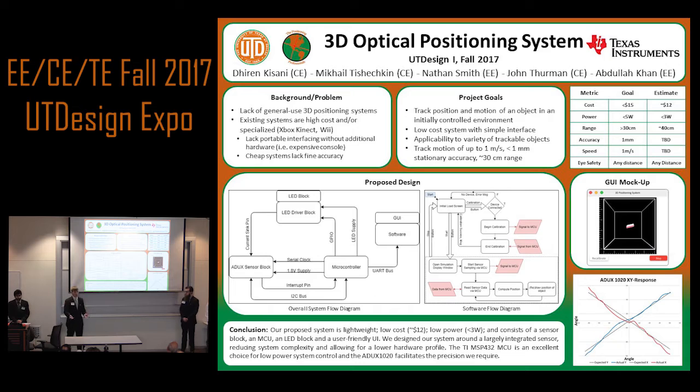It has the photo integrator, an integrated analog to digital converter, and an integrated LED driver. This significantly brought down the overall complexity of the system while slightly increasing programming complexity, and we felt that increase was more than worth the lower hardware profile of the whole system.